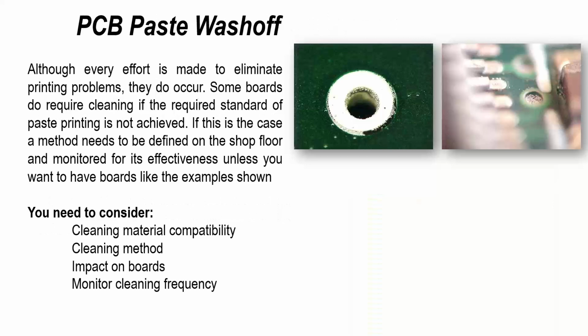Now, wash-offs in the real world happen. Ideally, you want to avoid them. But if you are going to wash off a board or boards, you need to make sure the cleaning material you're going to be using is compatible with the solder paste. It's just like cleaning of flux residues. You want the chemistry to work with the paste.